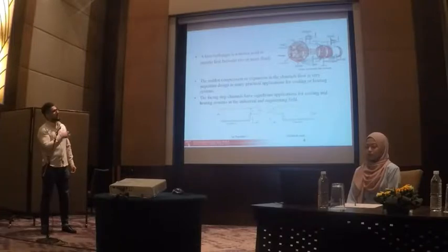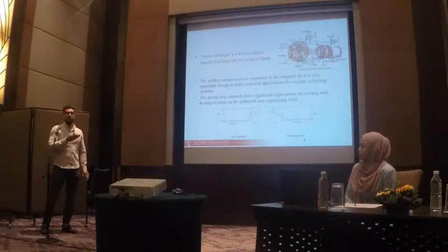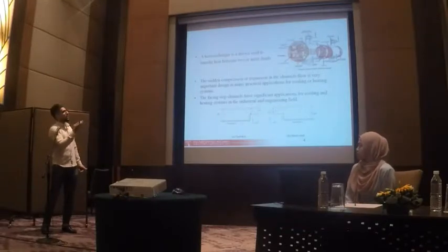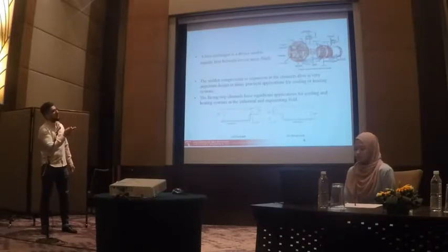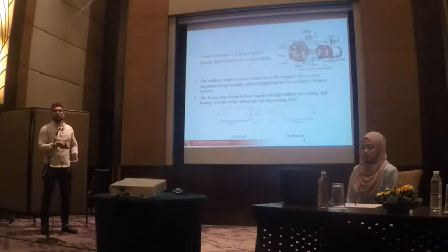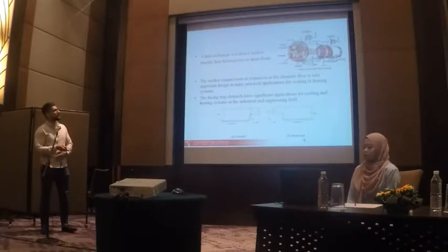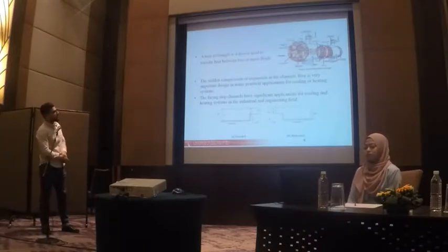Also, to enhance heat transfer, as we mentioned, we can use nanofluid, and we could change the geometry shape. Like here they use the circular tube, and other studies use square tube, corrugated tube, and facing step tube. You can see here down, the facing step.